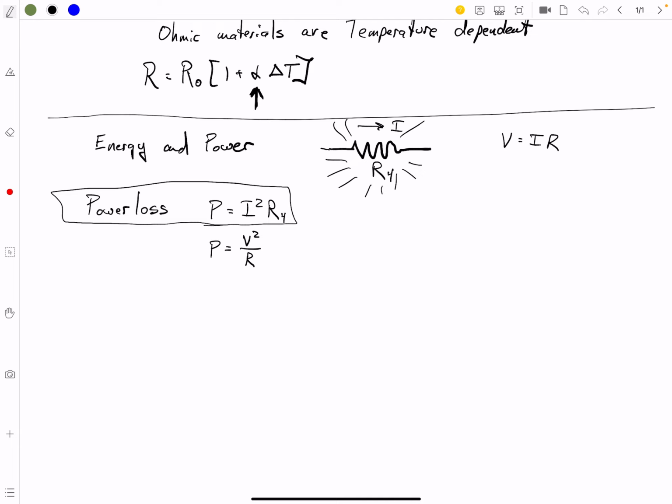If you try and get clever and do other things, you're going to make a mistake. I guarantee it. I've done it. It just doesn't work out. So when you want to know the power loss of a certain resistor, do the power loss of that certain resistor, okay? Otherwise, you're going to be considering a lot of other stuff that's not going to work for you. But that doesn't mean that this isn't applicable, and that can definitely be your power for a circuit.